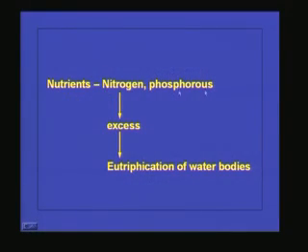But is it advisable to discharge high nitrate containing wastewater or treated water to inland or existing water bodies? It is not, because we know that nitrogen and phosphorus are essential nutrients for plant growth as well as microbial growth. So, if the nutrients are present in excess, what will happen? There will be excess algal growth in the water bodies, or eutrophication of water bodies will take place. So, it is not advisable to discharge high nitrate containing wastewater or treated water to water bodies.